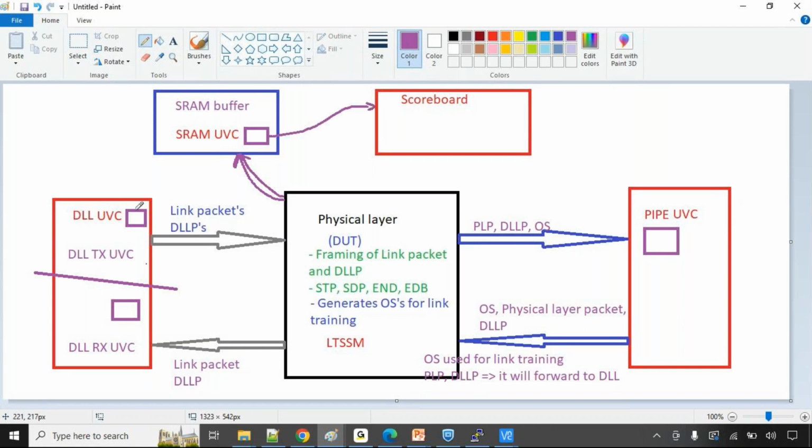This one also gets connected. All the monitors will get connected through analysis ports and implementation ports, and internally the scoreboard will handle these packets. This will also go here. So all five connections will come here and the scoreboard will handle them. We will see later how to implement the scoreboard. So this is the top level architecture of what we are going to do as part of this project. Do you have any questions up to this point?